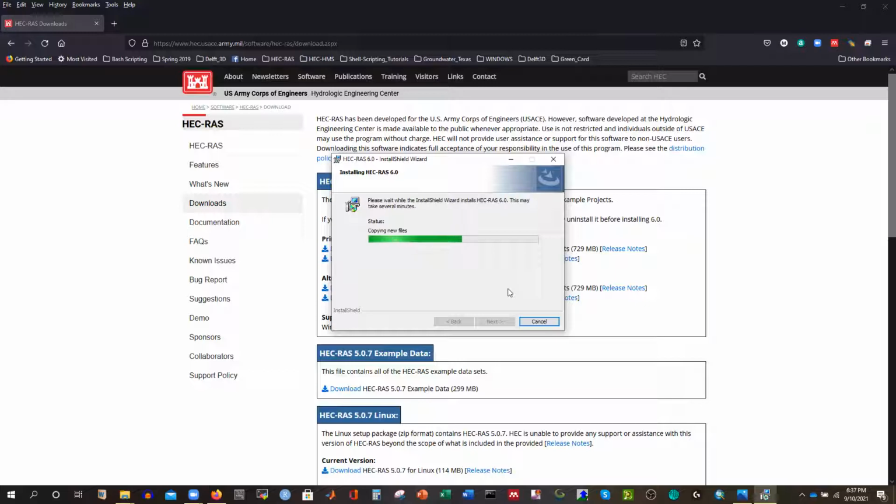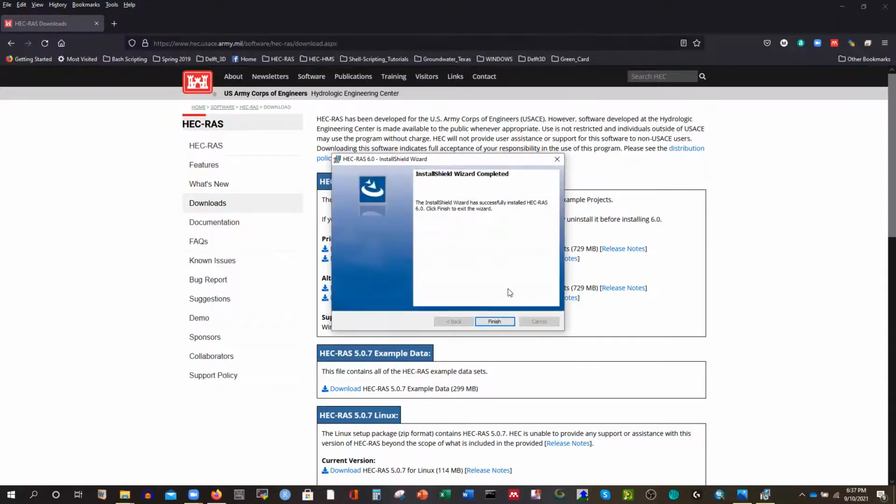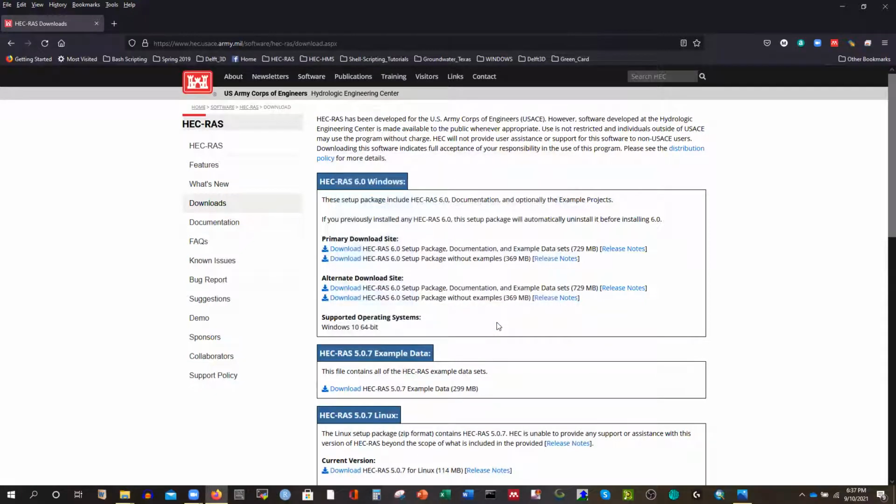What is the boundary condition at the downstream side of the river, and what will be the boundary condition at the upstream of the river? So usually what we do in hydrodynamic modeling or in hydraulic modeling, because this is hydraulic modeling, our upstream boundary condition will be flow rate or discharge, and our downstream boundary condition will be water level. So how can we fix that boundary condition, right?